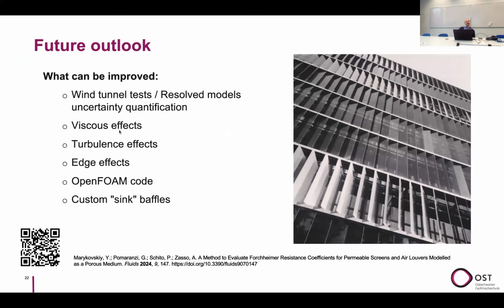Another thing is it would be nice to consider viscous effects. As I said before, we had to disregard them to have an analytical solution of the equation. Or turbulence effects, the same. Those are not considered. The topic becomes exponentially complicated, because there is a need for closure models and things like that. The edge effects are not considered. As I said, I assumed an infinite screen in all directions when deriving the analytical equations, so what happens close to the edges is not what the model is going to simulate.